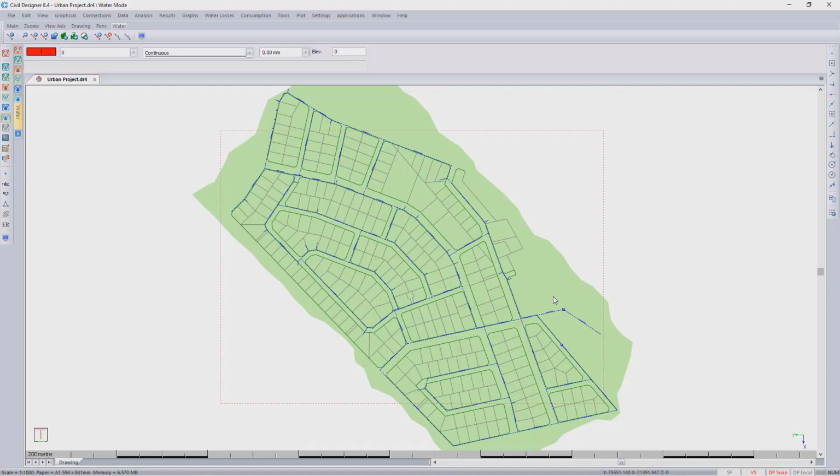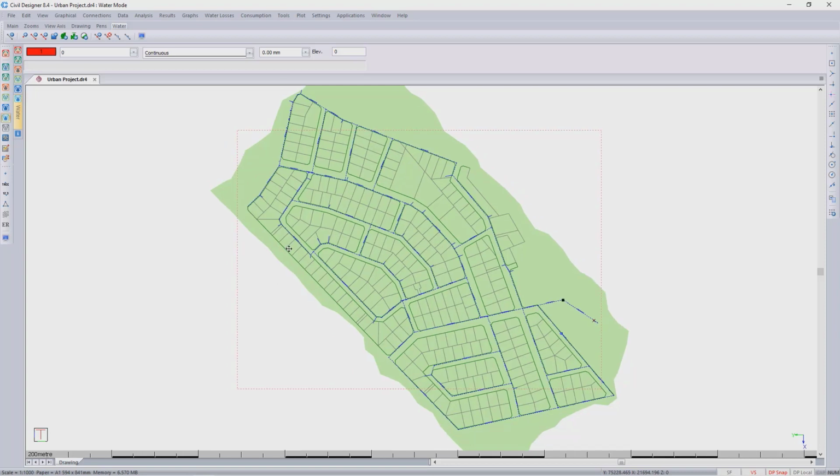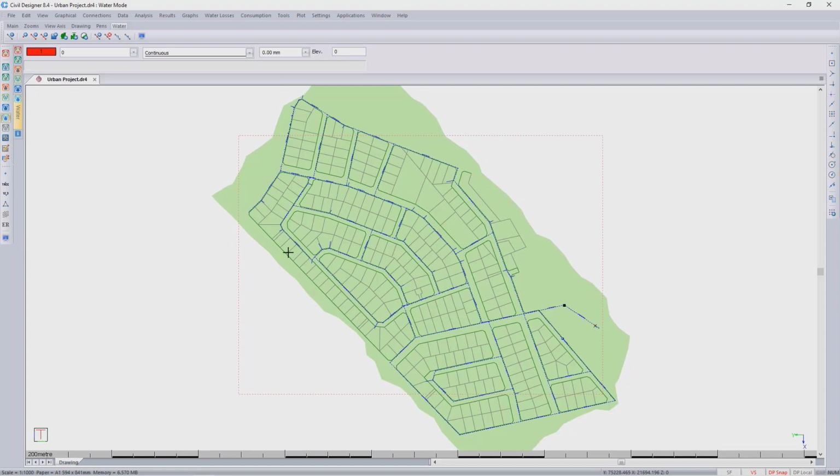The first part of running your fire flow analysis is to actually look at a completely other part of the project, and that is to look at the reticulation itself. Is it in order? Are you happy with it? Look, there might be changes with your reservoir capacities after you've run the analysis, or maybe you have an existing network and you're going to have to build a new reservoir to make changes for perhaps your town's got new specs for firefighting.